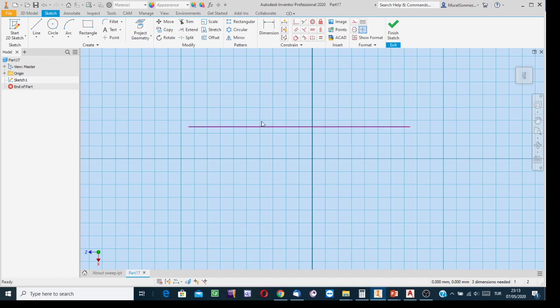Horizontally oriented or vertical, well, the orientation in sketch mode is not so important. For the dimensional constraint, the length of this line depends on the shortest distance between the inlet and exit of the loft. In this example, it is 2 meters, 2000.